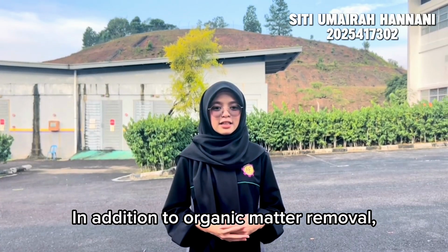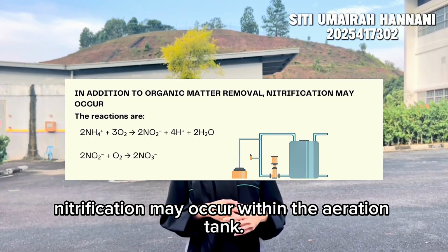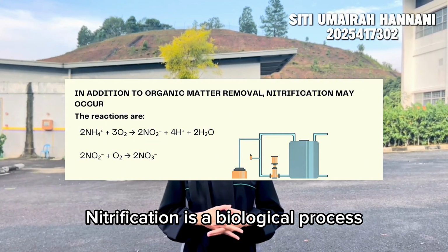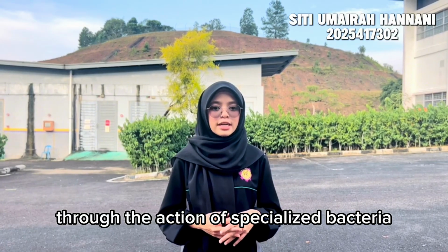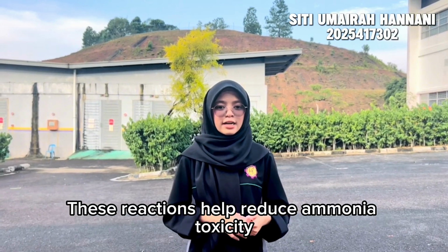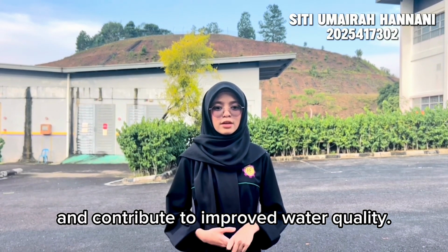In addition to organic material removal, nitrification may occur within the aeration tank. Nitrification is a biological process in which ammonia is oxidized into nitrate through the action of specialized bacteria. This reaction helps reduce ammonia toxicity and contributes to improved water quality.